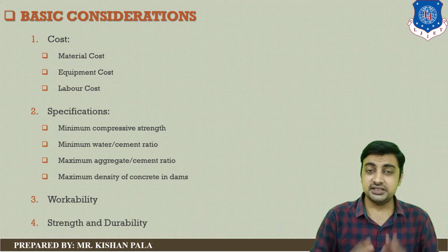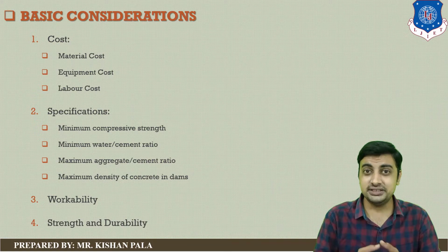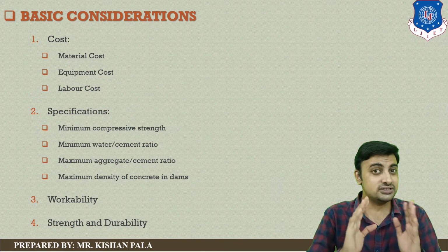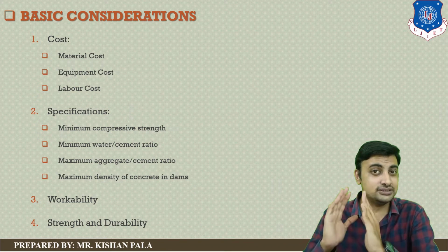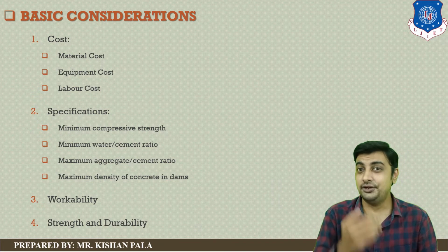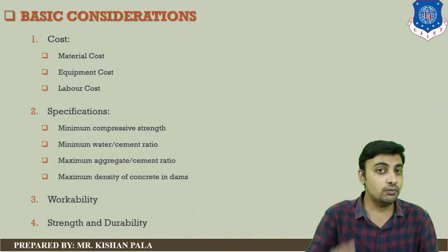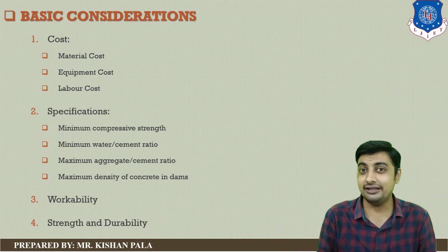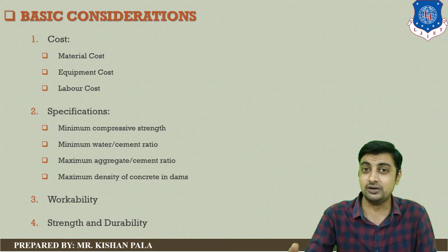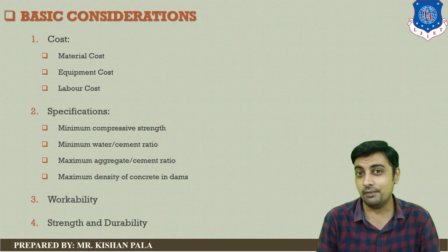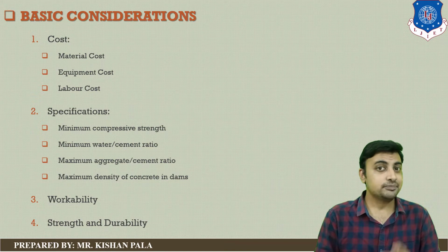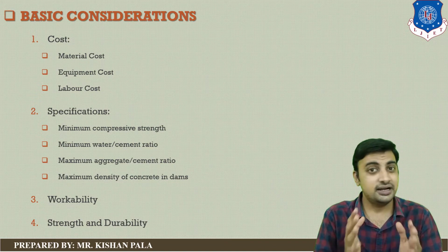And the fourth point is strength and durability. In mix design, the water cement ratio directly affects the strength as well as the durability of the concrete. You can achieve higher strength and durability with a lower water cement ratio, and if you add more water to your concrete, this will affect the strength as well as the durability of the concrete. So you have to consider this specification while you are doing the concrete mix design.